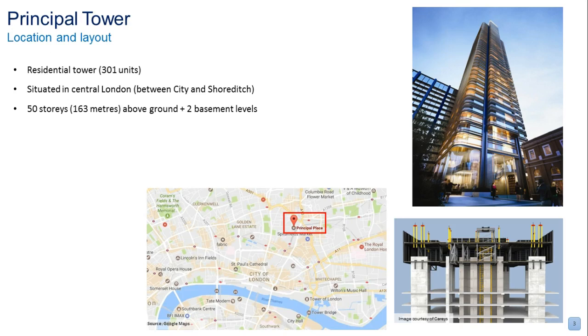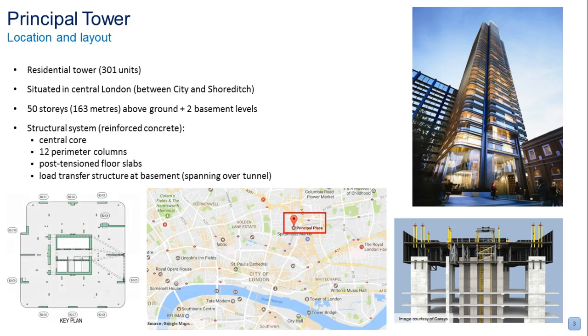It's a residential building, 50 stories tall above ground. It's about 163 meters, plus two basement levels underlying it. The structural system seems pretty standard. It's got a central reinforced concrete core, 12 perimeter columns, also reinforced concrete, and post-tension concrete slabs in between.